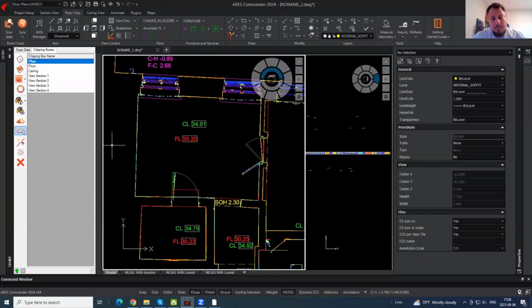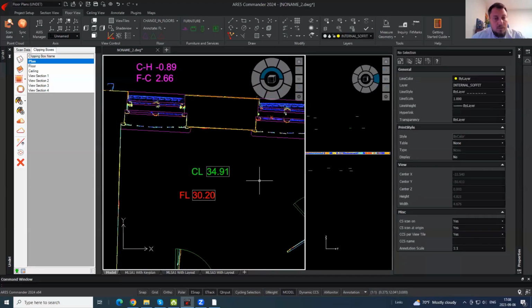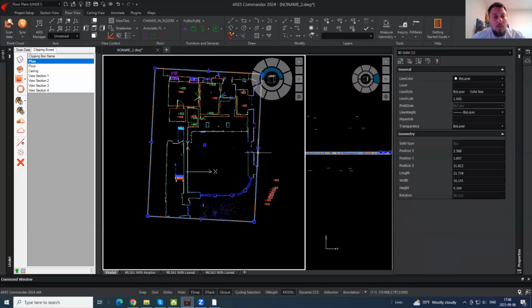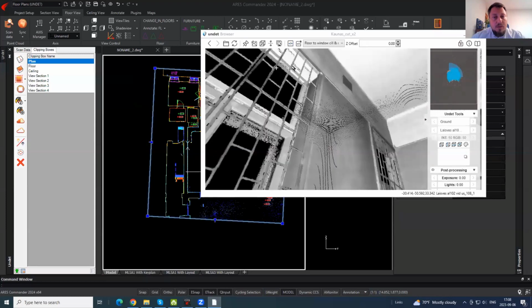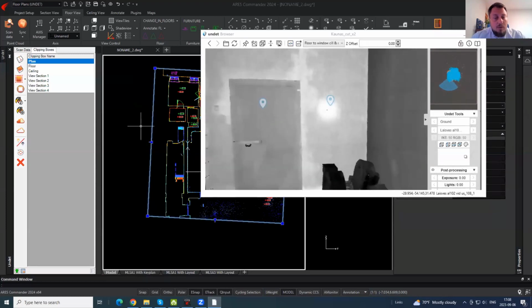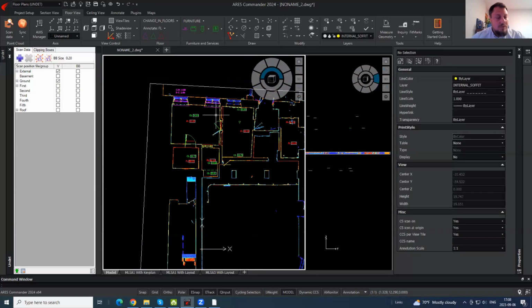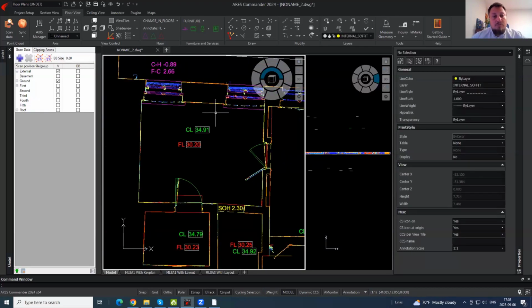Later on, we fill the drawing with the objects which are visible in the floor view, later in the ceiling view, inserting doors, windows, other types of blocks, and later on, if the customer asks, we place the annotations. What type of annotation should be inserted in the drawings, levels, heights, depends on the task which drafters usually receive with the point cloud.